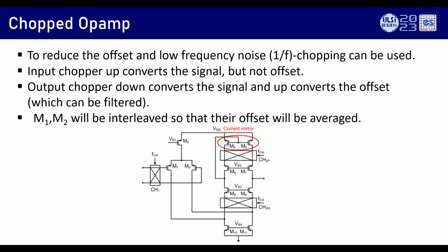So the way you do chopping is that you cannot do chopping on high impedance nodes. Couple of takeaways: don't do chopping in high impedance nodes. Always do chopping in the low impedance nodes. Otherwise, you'll be affecting the DC gain. For example, you put a folded cascode. You do chopping on the low impedance nodes, on the PMOS sources and the NMOS sources. Don't do it at the output. Okay, it's a pain.